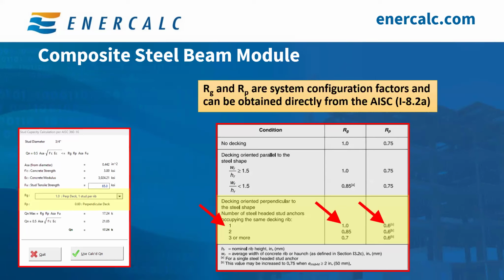If you want more shapes and sizes, you can click on this lookup button right here, and you will get a pop-up window where you'll have a larger database. So you can select additional types such as C and MC, and you can of course do a user-defined section right here. So you can actually click on this and define your own section with your own geometry, and that will be used for the calculations.